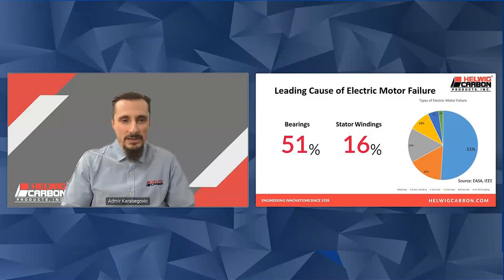So what's the leading cause of electric motor failure? Well, you have two main leading causes: the stator windings and the bearings. Now, the majority of the motor failures will be due to bearings. The 51% is both electrical and mechanical bearing damage.